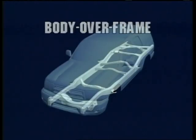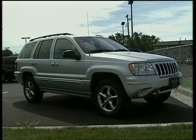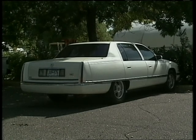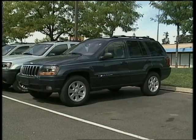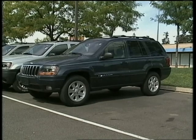There are two basic types of auto body construction: body over frame and unibody vehicles. There's also a variation on the unibody called the space frame. In body over frame, the frame provides the basic structure for the vehicle and supports most of the drivetrain and mechanical accessories. Examples of body over frame vehicles include pickup trucks and many SUVs. The steel panels of a body over frame vehicle are mostly cosmetic. Damage to these vehicles can be either cosmetic or structural, but not necessarily both.